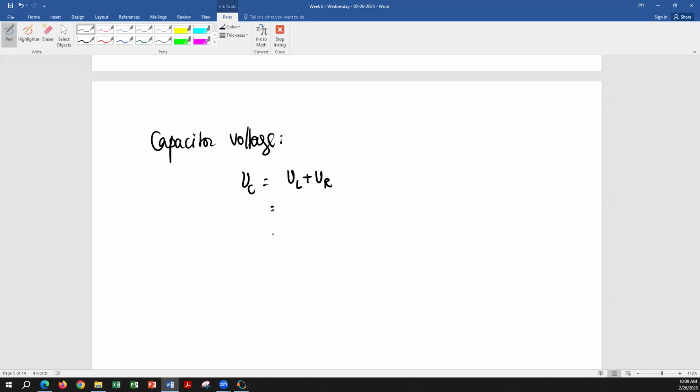Well, no, they're not the same. Capacitor voltage at zero positive is going to be the same as at zero negative, and inductor current will be the same at that instant. So these two quantities are not going to change instantaneously. Now, if you have other resistors in the circuit, then their voltage is going to change. The resistor current may change based upon how the switches are oriented. But these two quantities are not going to change. What do you mean when you say these are the same? It is a series circuit, yeah, through each component.